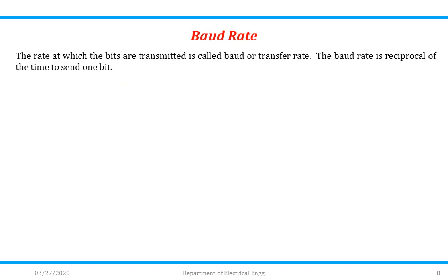Next we will discuss the baud rate. But before that, understand this very important concept. In case of Arduino UNO, simultaneous serial communication over USB and RX TX pins is not allowed. Okay. Now let's understand what is the concept of baud rate.